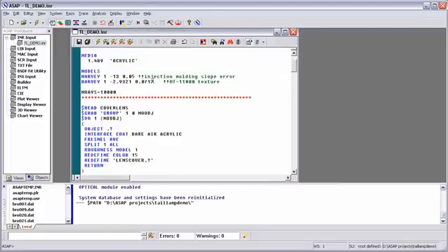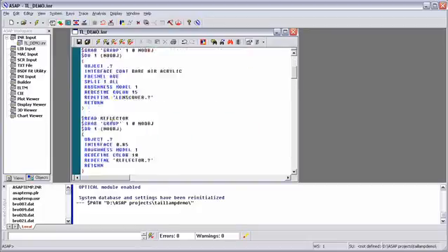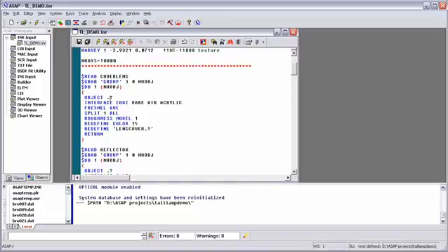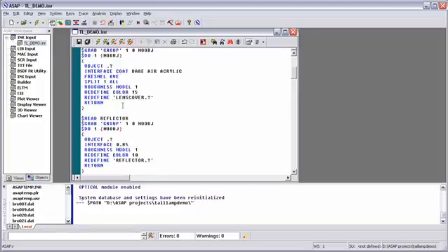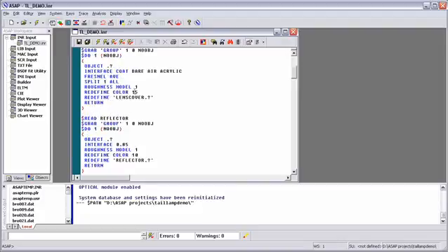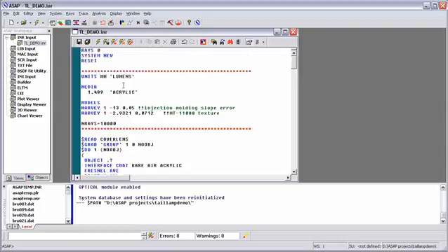I've set up my script file ahead of time to simulate the part, and we're going to simulate the cover lens, the reflector, and the optical surface that we just created. One of the things I mentioned before is that we skipped the material assignment in the IGES translator because inside my script in ASAP I can use this do-loop construct that allows me to set my material properties for each one of those components. And what this allows us to do is to change material properties quickly on each one of those components. And we'll look at that a little bit later.